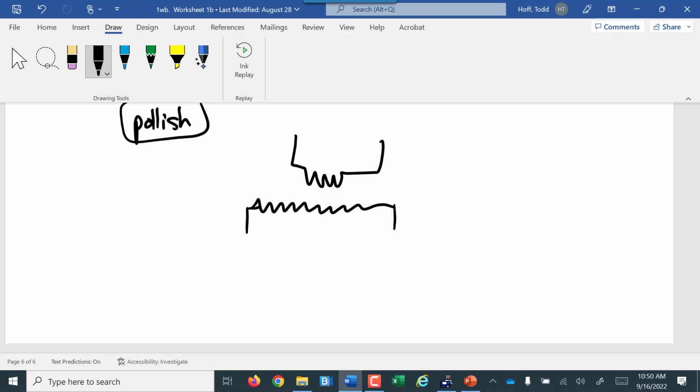You do want smooth surfaces. If you have a shaft that has a surface that's the consistency of sandpaper, it's going to grind away at any sort of bushing that it's turning in. Not good. So you want to have it polished enough that it eliminates the mechanical resistance, any sort of binding interaction, any intertwining between the surfaces. Polishing itself, though, once you've eliminated the mechanical resistance, does not reduce friction. In fact, it can cause other problems.